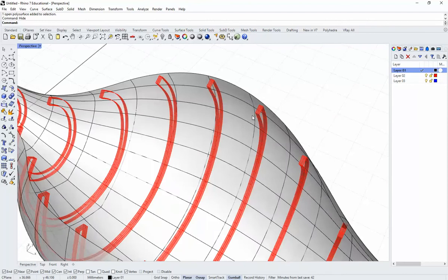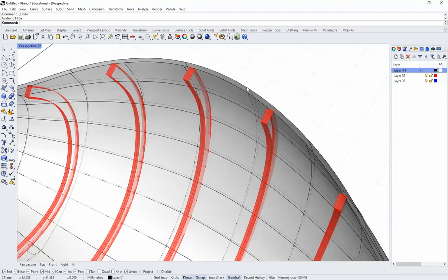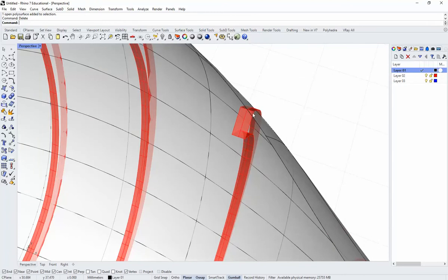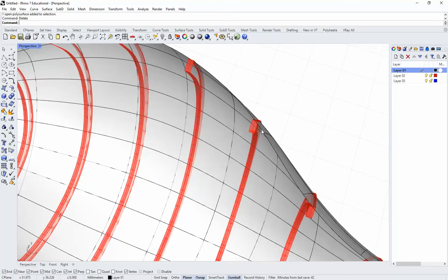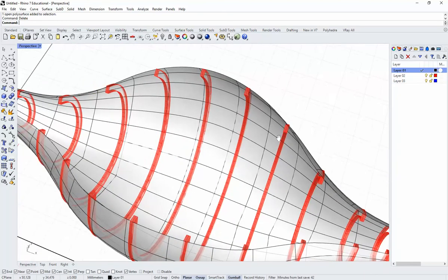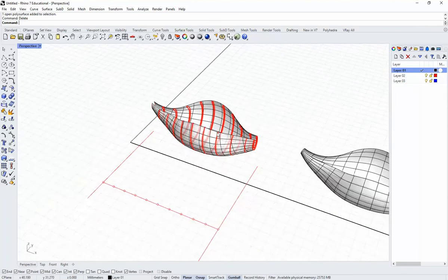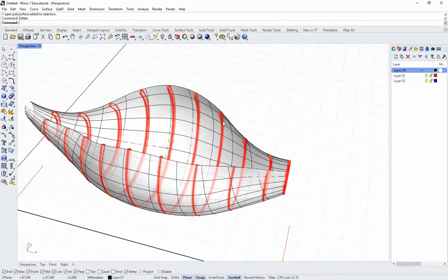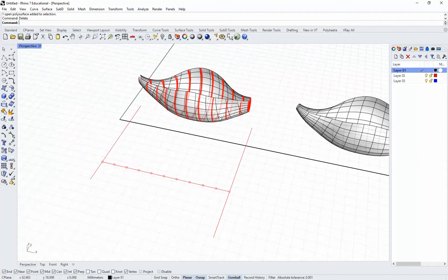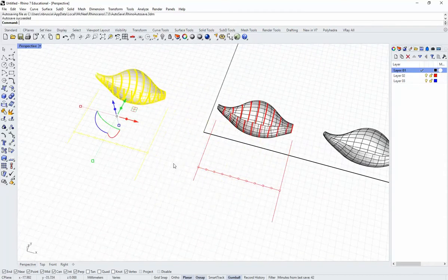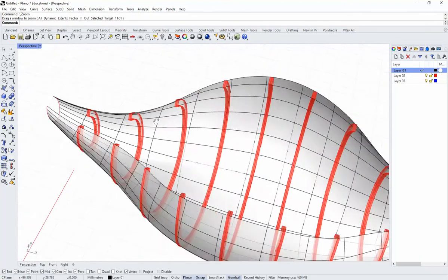Or it may not be good enough. So we'll have to look at it a couple different ways here. If you really want to be sure that it's touching only one of these edges, you can either duplicate those edges and rebuild the surface, basically doing a re-lofting, or what we can do is just be a little more careful with how we're extruding those structural elements. This is the case if we want them to be on center. But another thing you can do, if you had already given some thought to the spacing, is extrude them such that they don't.